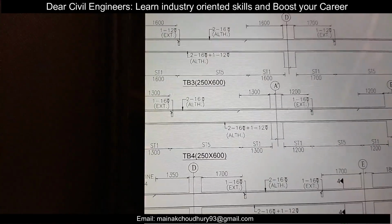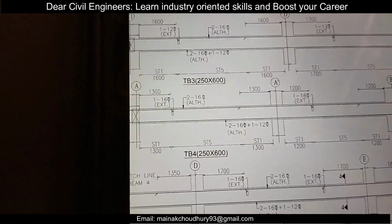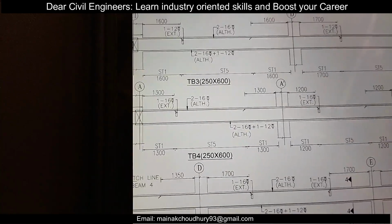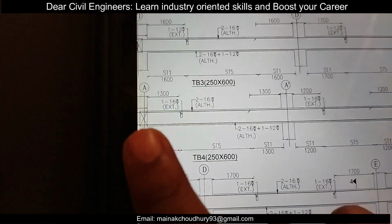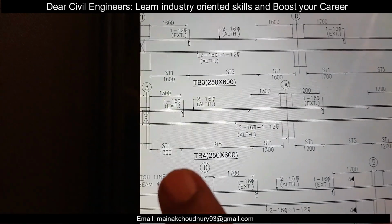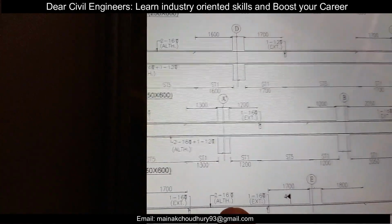So if we talk about the all-through bars, the continuous bars, ALTH, which will go all through. At the first span, at the top there are 2 bars of 16 mm, and at the bottom there are 2 bars of 16 mm and 1 bar of 12 mm. And similarly for the extra top, we have 1 bar of 16 mm up to a distance of 1300, and there is no extra bottom bar in this first span.